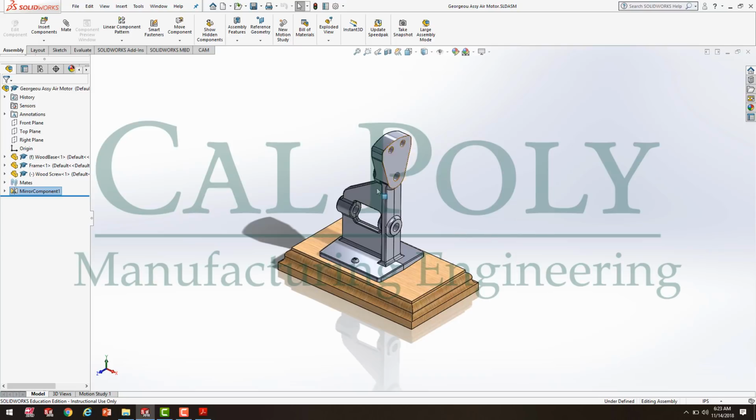So now looking at the air motor, I've got to create a couple more assemblies. I could do sub-assemblies outside this assembly environment, or just physically put it all together now. For example, I could press fit the main shaft into the flywheel as an assembly, and then bring it into this assembly file as a sub-assembly, but it might be easier for now to just insert all the components into one file.